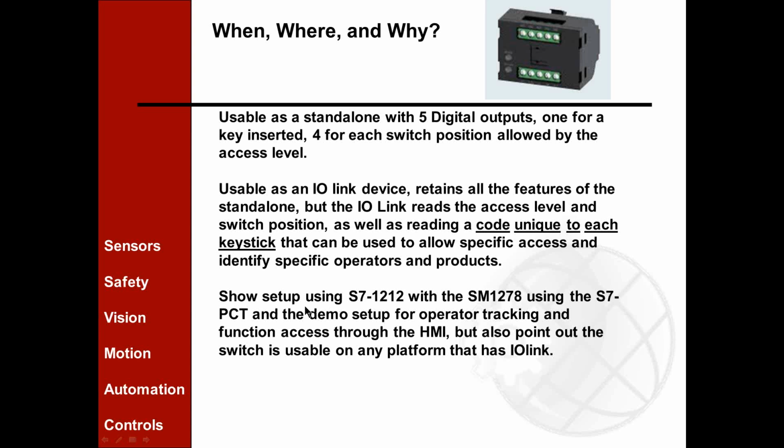You can show the setup. Oh, I'm just reading off of here. But anyhow, we did this setup with an S7-1212 and an SM-1278 I/O Link Master, which has 4 I/O Link ports available to it, and we used the S7 port configuration tool to do this setup. We showed a little bit of the demo and went on there live without getting into too much trouble. The switch is usable on any platform that has I/O link.